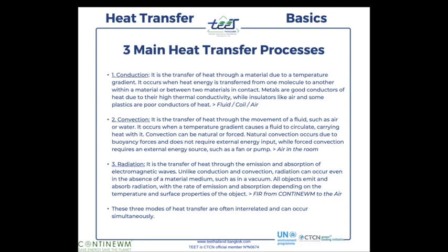Okay, so the coil is a place that we call a heat exchanger, basically, because you have two heat exchanges, actually. You have the heat exchange from the fluid that is inside the coil, be it water or be it refrigerant fluid, and the heat exchange between what is outside the coil and the coil itself. So you have the metallic coil, because the coil is metallic, is a place where you have a lot of heat transfer from outside of the coil and transfer from outside to inside of the coil, okay?